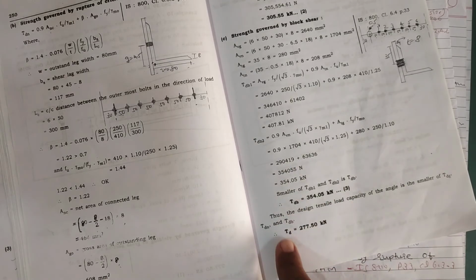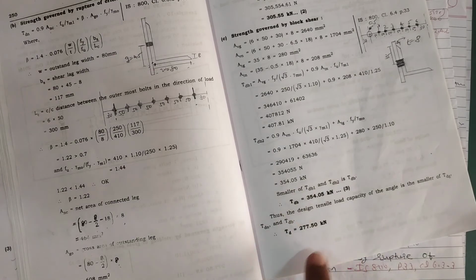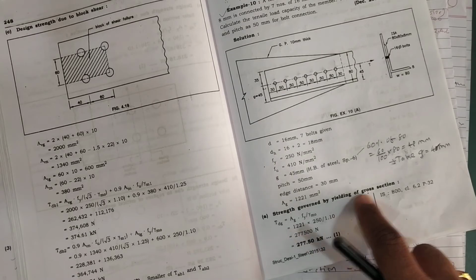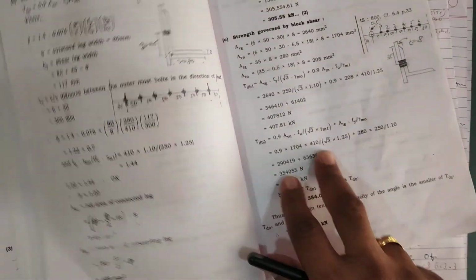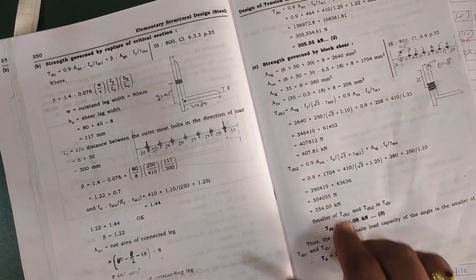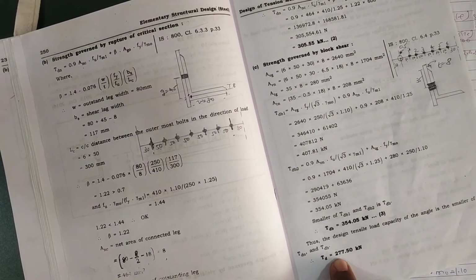Okay, and what is the final answer? The final answer is the minimum of the first three answers. What are the three? One is the strength governed by the yielding of the gross section. Second, strength governed by the rupture of the critical section. And third, strength governed by the block shear. So the minimum of the above three comes to